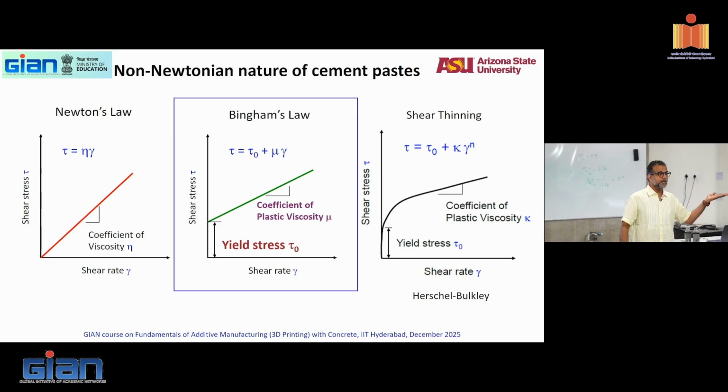They're called shear thinning. Now, there are some liquids, when you cook with some sauces and all, if you put in a little bit of flour and start to mix, what happens if you start to mix more? It starts to thicken up. They are called shear thickening. So you have shear thinning fluids and shear thickening fluids, right? Concrete typically is a shear thinning fluid, and that's why as you mix more and faster in the back of a truck, the concrete becomes more and more flowable, correct?